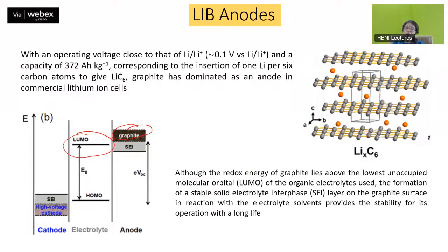And because this particular SEI layer is formed, definitely there is going to be some loss of lithium, because the lithium is coming in from your cathode and the cathode has a particular reserve of lithium. LiCoO2 has this much of lithium. Out of which some of the lithium you cannot use, because it is giving that irreversible reaction of formation of the SEI layer. So that much amount of lithium cannot shuttle back into your cathode. So that is lost. So you will lose a little bit of the capacity.